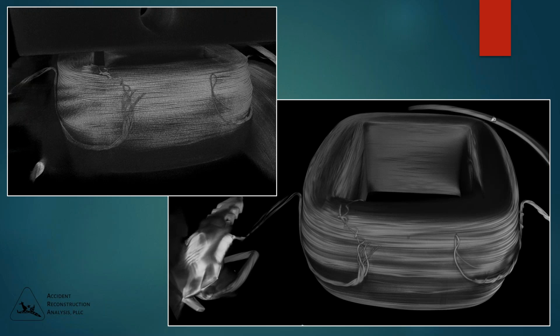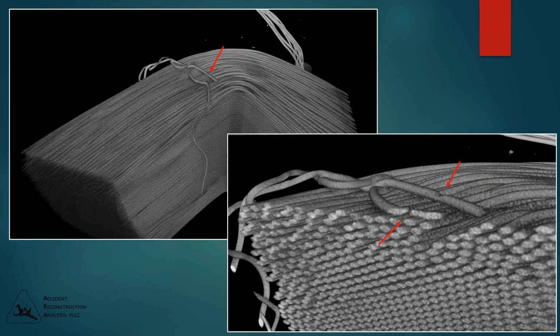So you can see the terminal lead wires coming in here, then being attached to the magnet wire spliced areas. The OD attachment is on the right in the bottom right image, and the ID attachment splice is on the left. So here's a more magnified image of the magnet wire coming from the ID. And if you look at the image at the bottom right, which is magnified from the one at the top left, and sectioned along the